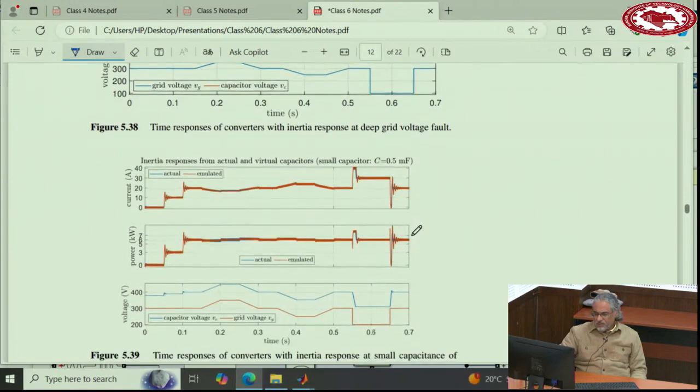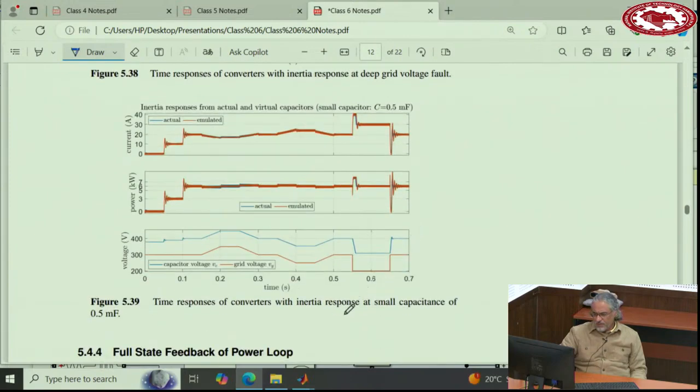Now, this simulation here is an extreme case. When you reduce the capacitor very small, it's not really very important, because anyway we do not decrease the capacitor too much here because we want to have inertia, right? If you decrease it, you don't get a lot of inertia. You really get a tiny amount of inertia. So inertia is very small, but what happens, oscillations start appearing on the responses. And later I have discussed in the next little section here how you can remove these oscillations.